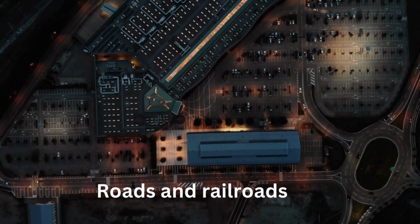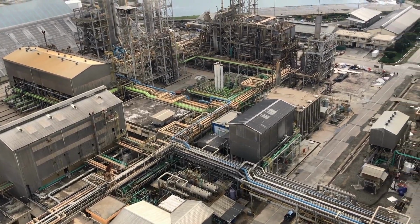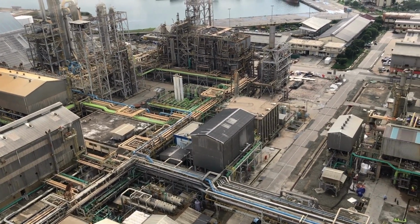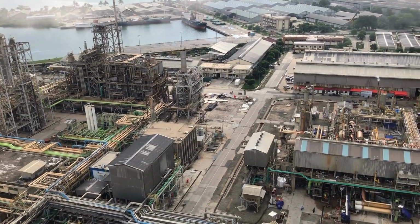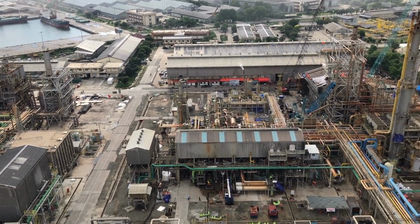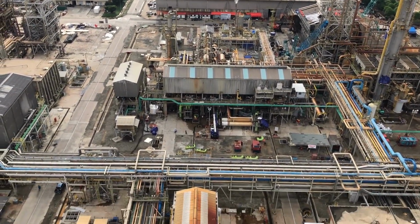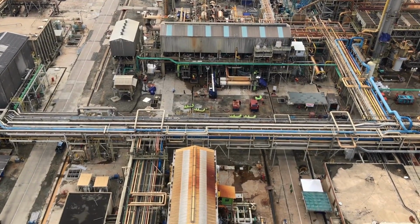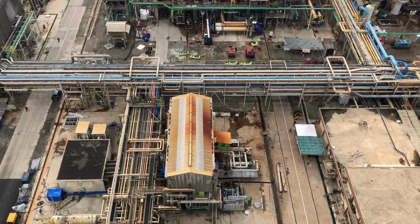Possible future expansion. Once we finalize the process flow diagrams, then before detailed piping, structural and electrical design can begin, the layout of process units in a plant and of equipment within these process units is planned. Next is preparation of drawings and elevations, including isometric drawings of the piping system, equipment elevations etc.